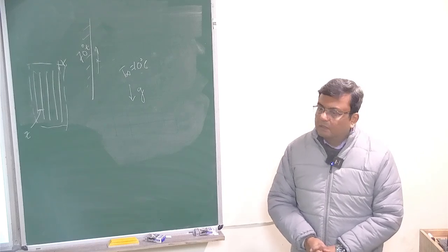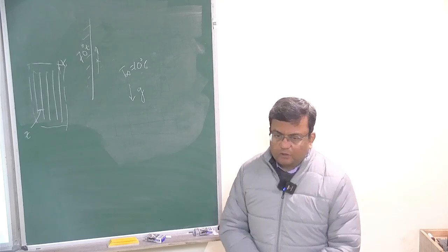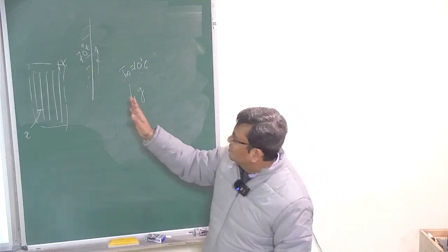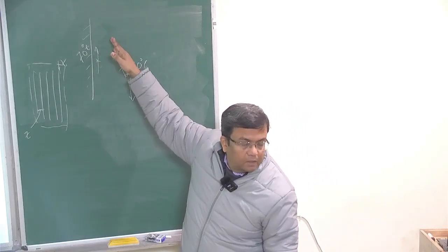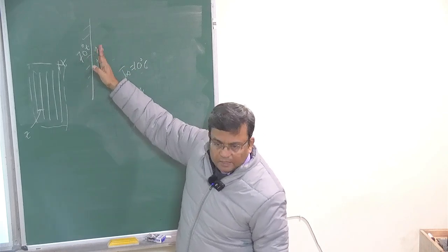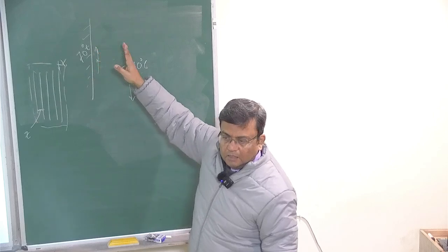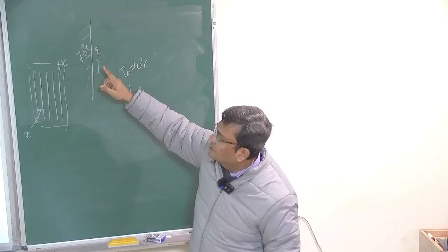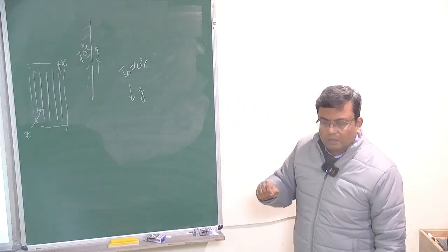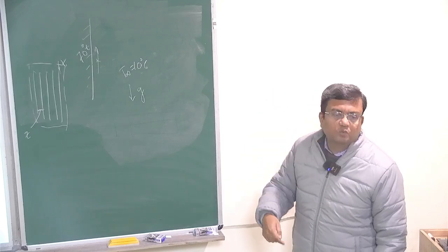There will be viscous effect also, fluid friction, which will try to oppose this fluid that is trying to move up. Next to the surface there are slow moving layers of fluid, and the layer of fluid right next to the wall is actually at zero velocity. So they're trying to drag this fluid downwards.